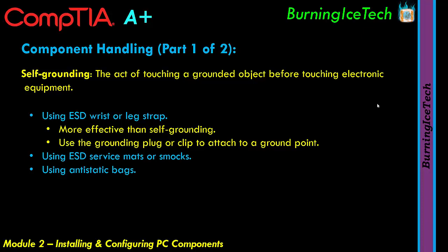Something you should keep in mind though, if you're going to do that trick of mine, is as soon as you start walking around, especially if it's on a carpet or something like that, you immediately start building up static again. So you want to keep completely still. If you for some reason need to walk away for a few steps, as soon as you get back, get into the habit of just automatically touching that metal frame of the chassis again. As soon as you do that, you're going to discharge again, and then you can start touching the motherboard. It's a difficult habit to build up, but once you have that habit, it's a good habit to have.